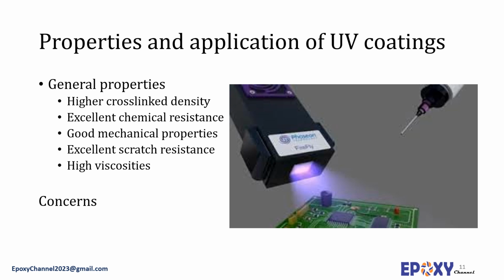The cross-linking density in cured UV coating is generally higher compared to most other cross-linked films. The presence of a C-C bound network structure results in excellent chemical resistance to acids and bases. UV coatings have good mechanical properties and excellent scratch resistance. The final flexibility of the film can be tuned by choosing resins and reactive diluents with different natures, which makes UV coating suitable for plastic parts also. However, UV systems are often used for wood coatings, for example, furniture, parquet sealers, and laminate sheets.